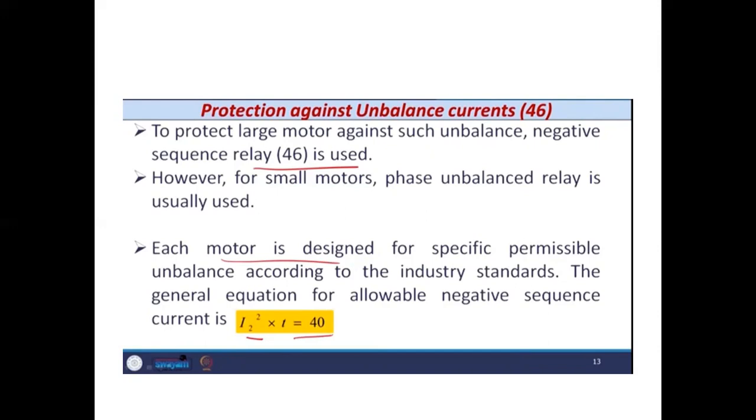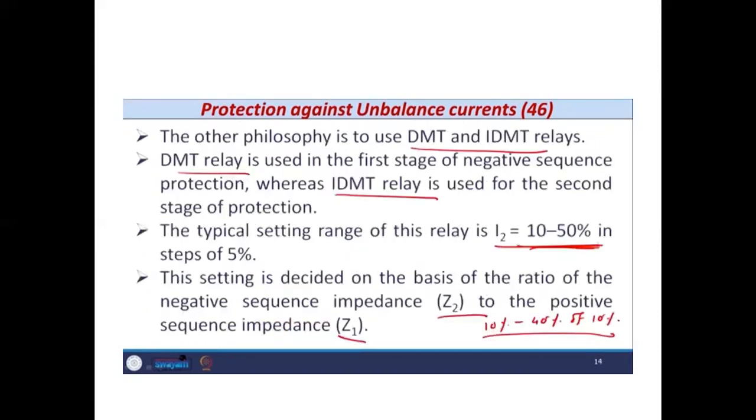The other philosophy: suppose I have a small motor and its cost is low compared to other motors, then it is not economically viable to use the negative phase sequence relay for protection against unbalanced currents.